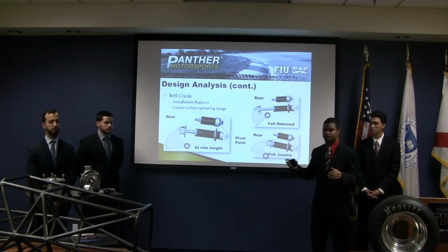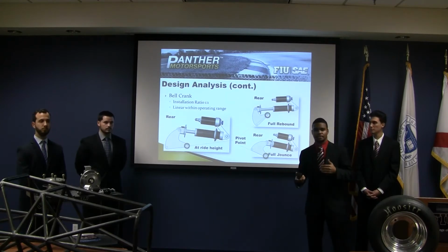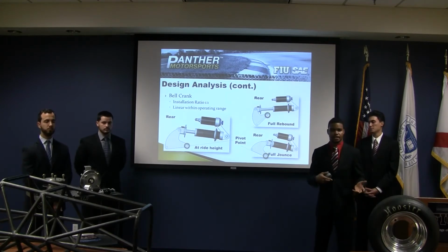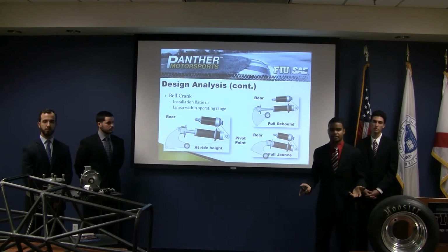So the installation ratio relates the vertical travel of the wheel to the linear travel of the shock and spring. And it's important to ensure that you're maximizing the use of your shocks and springs, because if not, then they're not going to perform effectively, and why bother have suspension?